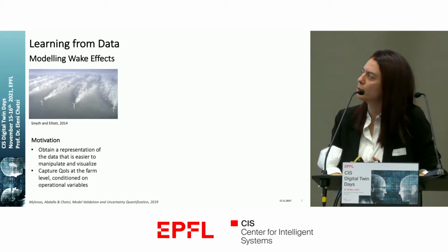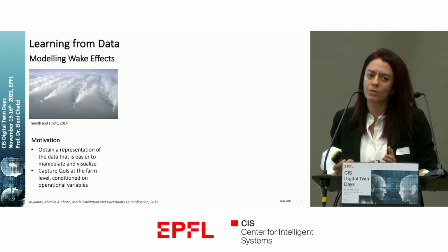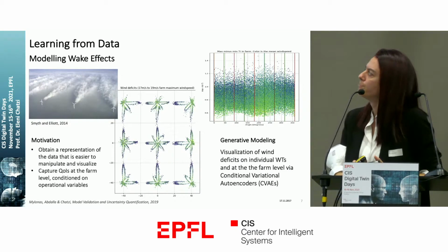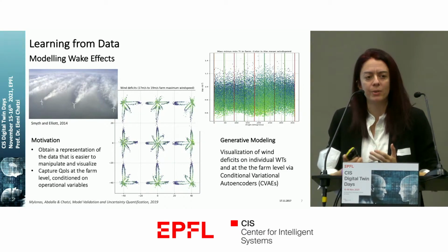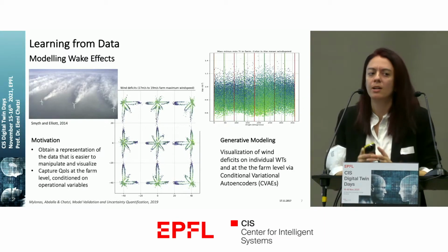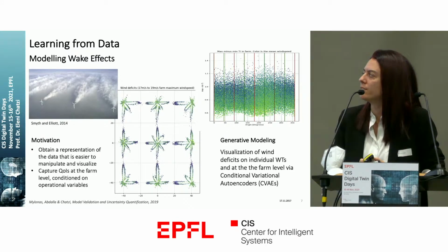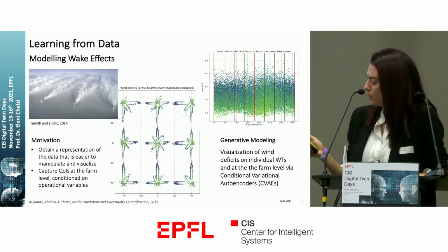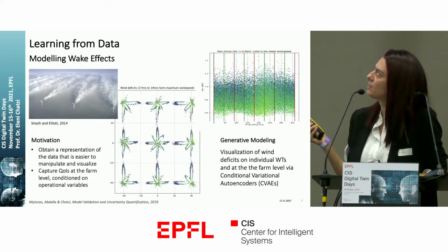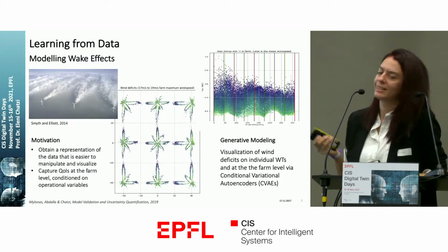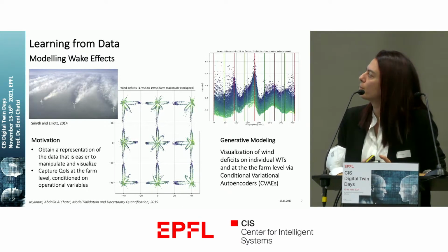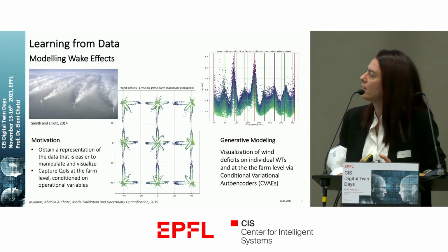And so in this project, we set out to use data that is readily available for wind farms to try and derive models of the interaction of turbines with each other, this wake effect that is caused by the orientation and the placement of turbines within a farm. And indeed, it is possible to extract information that is purely derived from data and that explains the way in which a turbine is fatigued, so you can extract engineering metrics that come just from the processing of this collection of SCADA information.